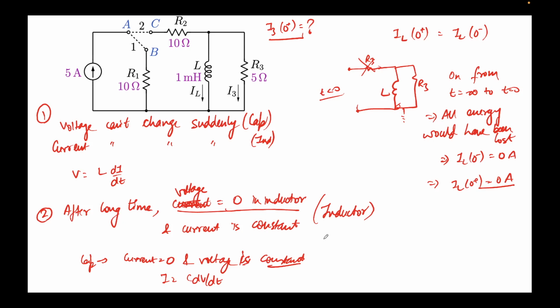Okay, just to reiterate this problem, because this is the first time that we are talking about inductors and when the switching is happening. This is the most important concept: the current cannot change suddenly whenever any switching or some step voltage or step current is coming. This is the only important thing that you need to consider.